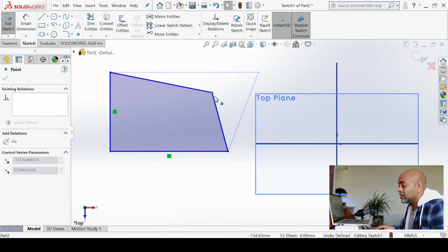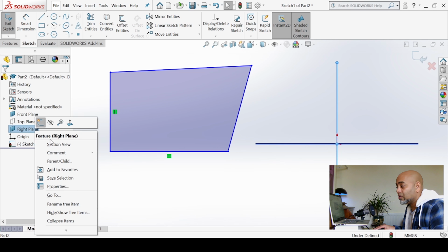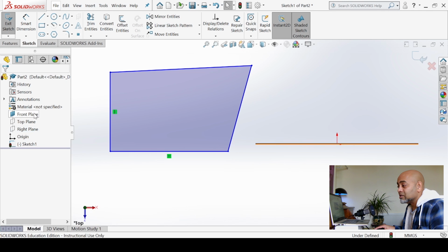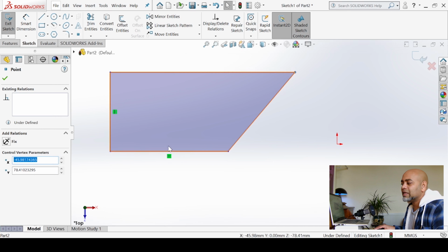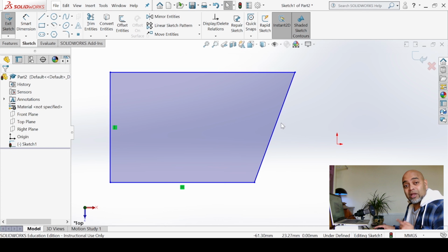Every time you are working in SolidWorks, it is necessary to keep an eye on little indicators like that. Most of the time you are trying to draw geometry and you think, actually, it's not functioning correctly. This is not what I wanted. What you're probably missing is a bunch of these little green indicators. These are the snap indicators or constraint indicators, which are dynamically present on the screen as you sketch. Sometimes you can delete those if you don't need them, or bring them back.